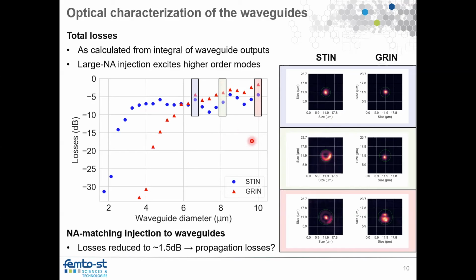In the second cut, we see that here there is this dip, and then poof, it shows that the second mode starts to enter for the step index, but not yet for the graded index. And then here I show a condition where actually we have even a higher order mode for the step index, and the graded index already is multi-mode, or let's say second mode entering. So with that, we can see basically these conditions are single mode for a step index, and in this range we have a single mode propagation for graded index.